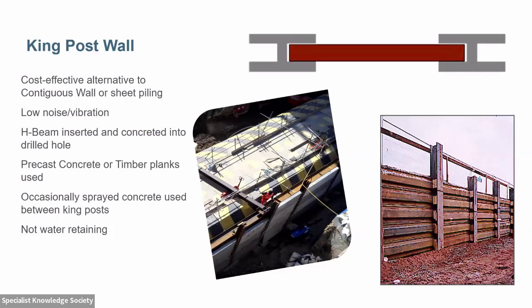Not used greatly in my experience within the UK, particularly for permanent works. There are some temporary works and fairly small excavations where you could use this kind of solution because it is quite quick and easy. Understanding in America this is used quite frequently for lots of their basement excavations, but it isn't a common retaining wall within the UK. Again, that's only based on my experience. Other people may have different views.